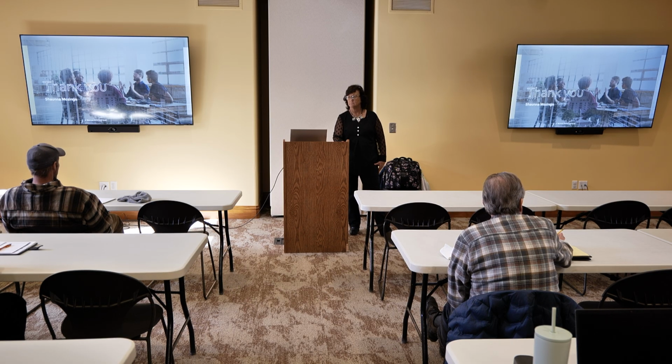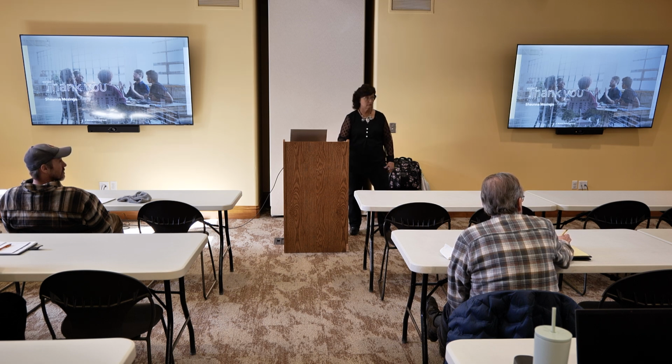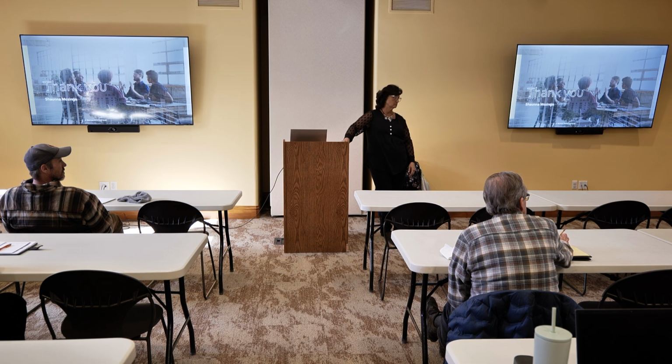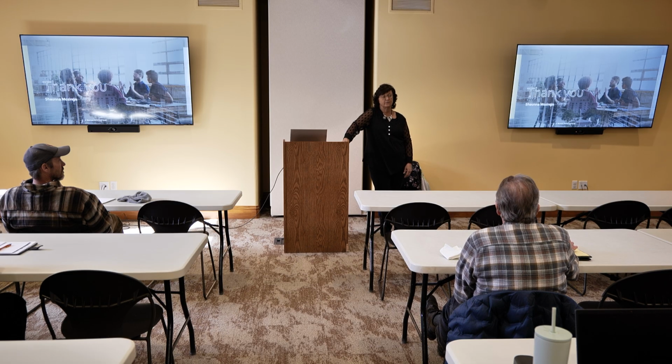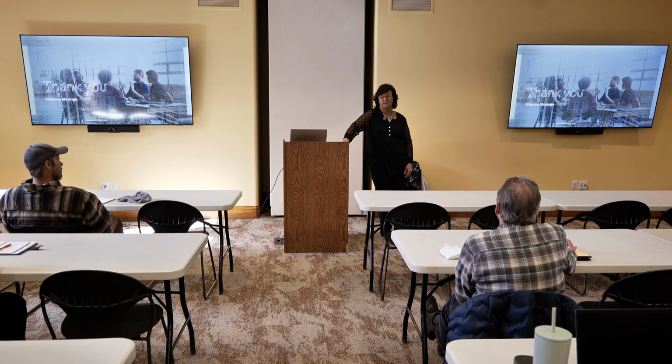What else? Yeah, we have 30% max fenestration, but you can get around it by doing the zero energy. Yep, you could go ZERH. It being above code and just has checks and balances where you can weigh that out. Yep. Extra credit in some areas where you're getting less credit for fenestration going over 30%. What I think you're going to find is it's going to be most beneficial and cost effective to go either ZERH or go ERI.